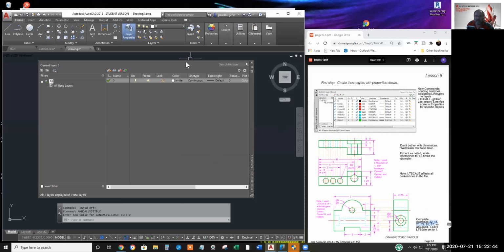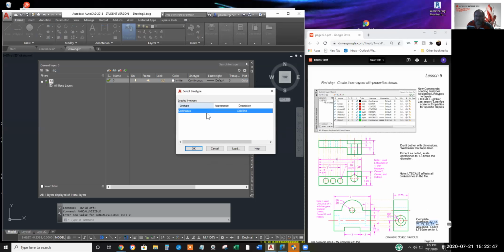Anyway, getting back here, when you click on the line type, you'd expect to have a menu. Unfortunately, the way AutoCAD was made back in 1982, hard disks were really, really small and computers were really, really slow. So the template file, acad.dwt, is minimum size and only has the continuous line type. Every time you load a line type to add it to your menu to be able to choose it for a layer, it fattens up the CAD file.